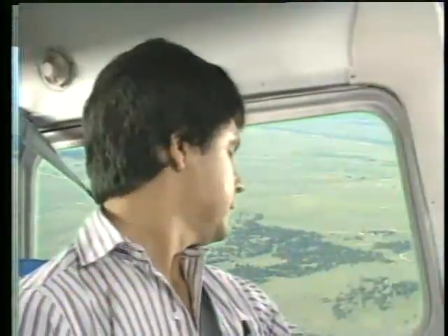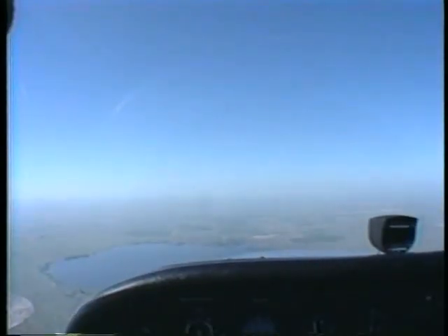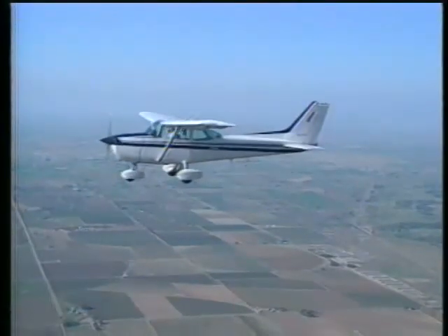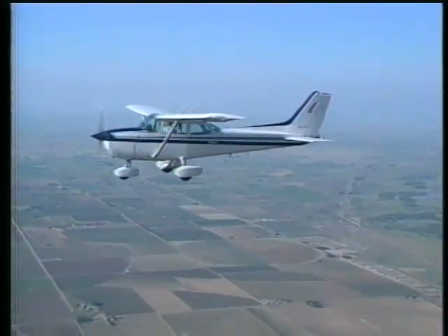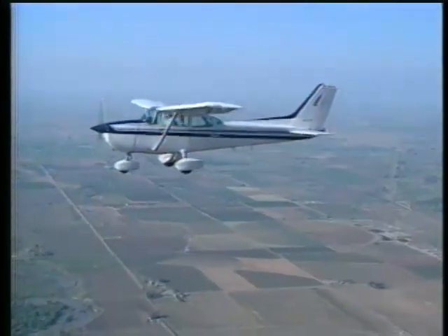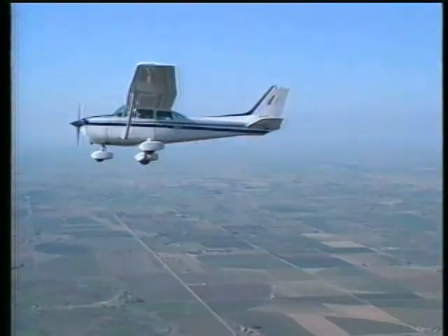Plan your approach so that your initial contact with ATC can be made when you are above a designated visual checkpoint or prominent landmark. "Jensen approach, Cessna 62740, over Prospect Reservoir at 8000 with Sierra, landing Jensen." "Cessna 740, stand by." Since the controller used your call sign, radio communications have been established. This means you can continue on course and enter the Class C airspace. If the controller uses the words, "Aircraft calling Jensen approach, stand by," radio communications have not been established, and you must remain clear of the Class C airspace.